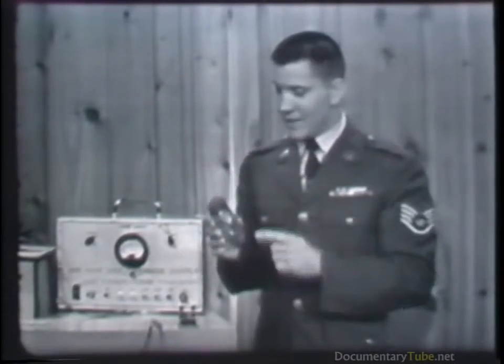Well, as a matter of fact, I've already figured it out, and approximately 70 turns of this 300 turn winding are indeed shorted. Now we see then that for a shorted transformer winding, the ohm meter will indicate a resistance less than the normal resistance of the winding. Now, of course, the greater the number of turns shorted, the greater the decrease in the resistance of the winding.